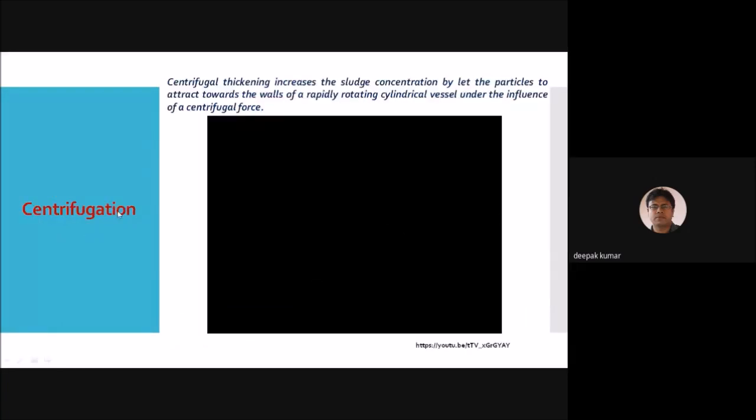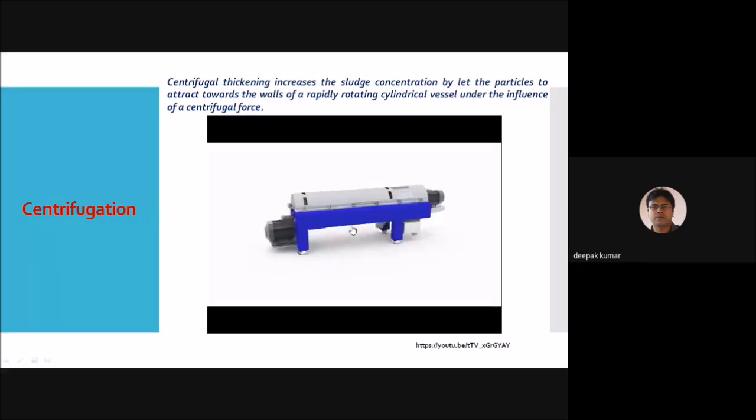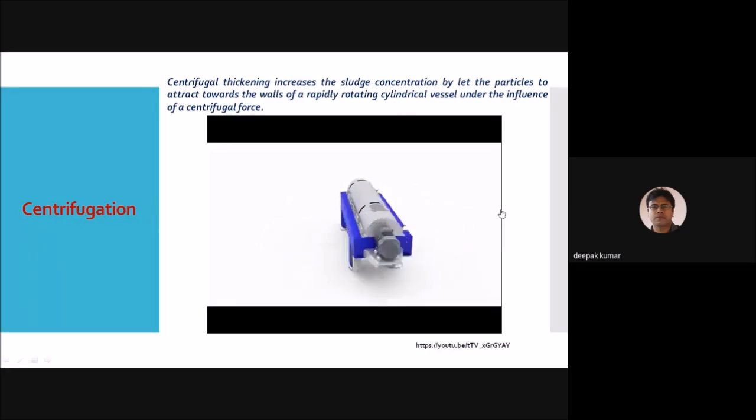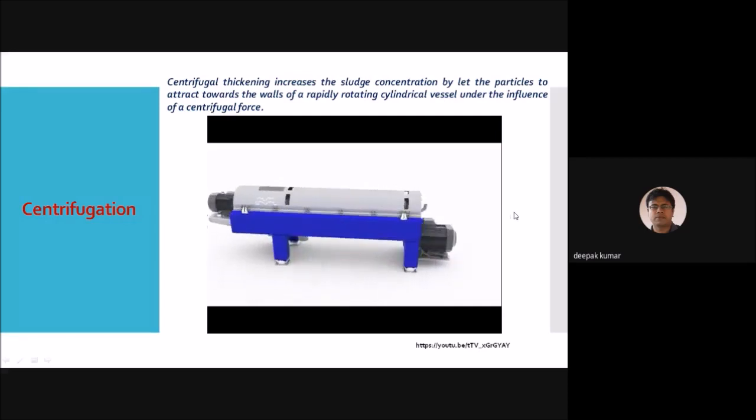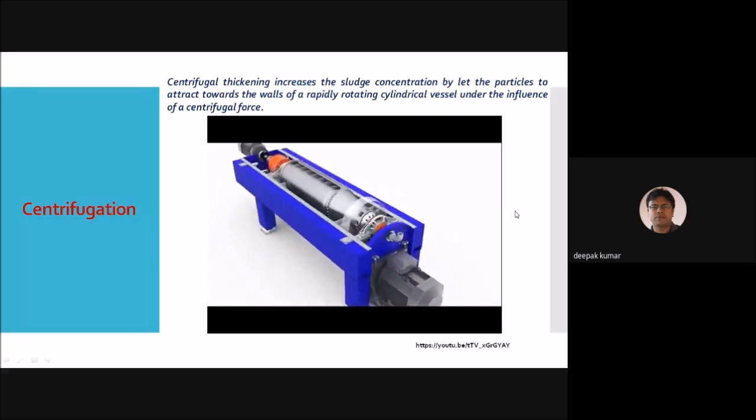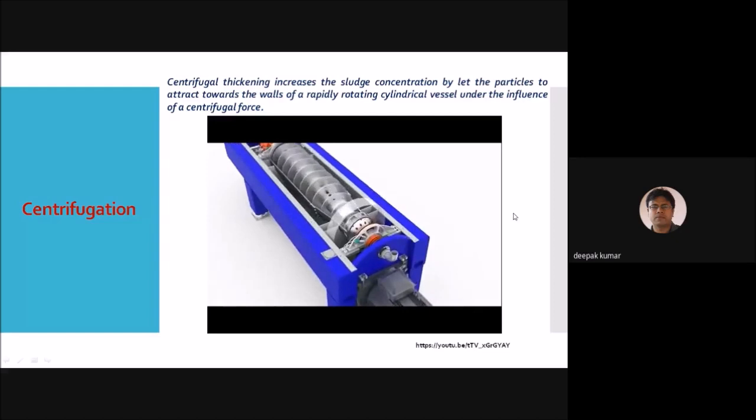Similarly, I am showing you a video of centrifugation. In this case, the action of centrifugal force will be used. So centrifugal thickening increases the sludge concentration by leading the particles to be attracted towards the walls of a rapidly rotating cylindrical vessel under the influence of centrifugal force. So you see,